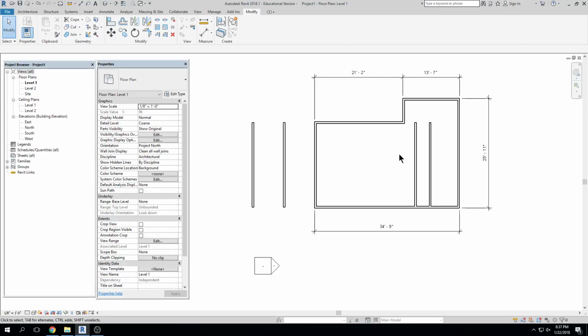So you're doing keyboard commands, you don't hit enter afterwards? No, there's no enter. Sorry, I may not have said that. When you're entering keyboard commands, it's a two key shortcut, and there's no enter after it. Instead of enter like AutoCAD, when you're creating an object, the space bar flips it back and forth.